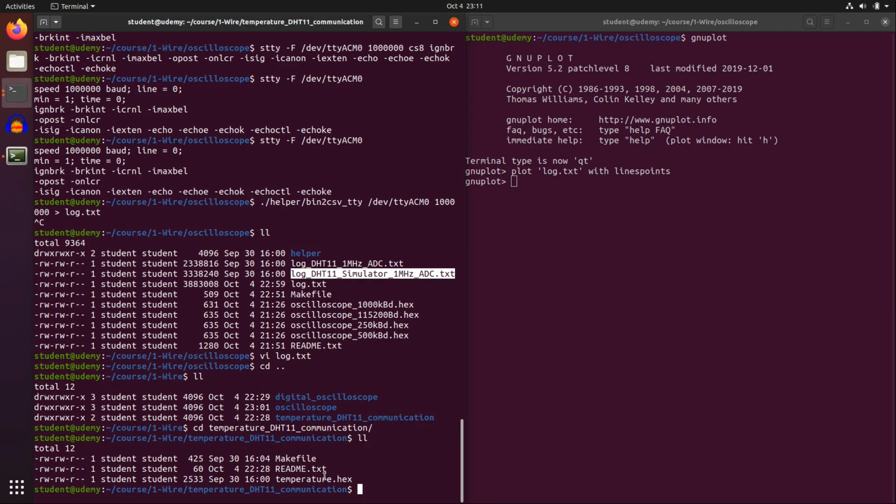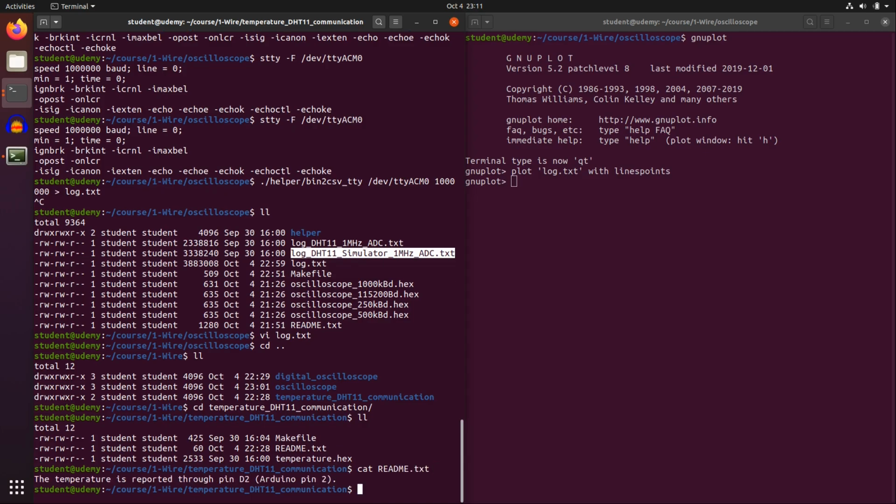It converts an ATmega into a temperature probe which supports the DHT11 communication protocol. And you have to connect pin D2 or the Arduino pin 2 to read out the temperature. The temperature is not that accurate. Don't worry if you read temperatures in a range of, for instance, 80 degrees. The temperature node of the ATmega is not calibrated, and its accuracy varies from chip to chip.